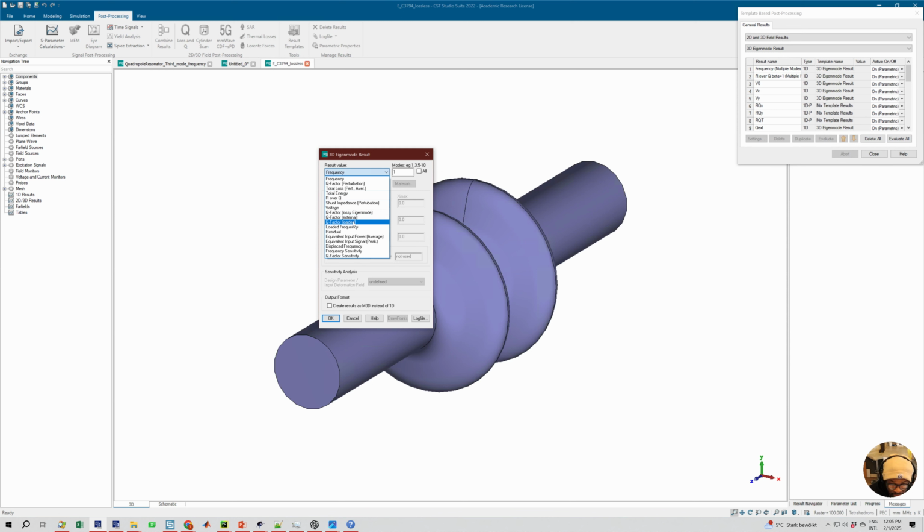And then you have the loaded quality factor, which is a combination of your Q factor perturbation, which is your intrinsic quality factor, and the lossy eigenmode or the Q factor external. So these two ideally should give the same or similar result. So now I'm thinking of it, probably I should run a simulation to compare these two. Maybe I'll do it because I've been on 2023.